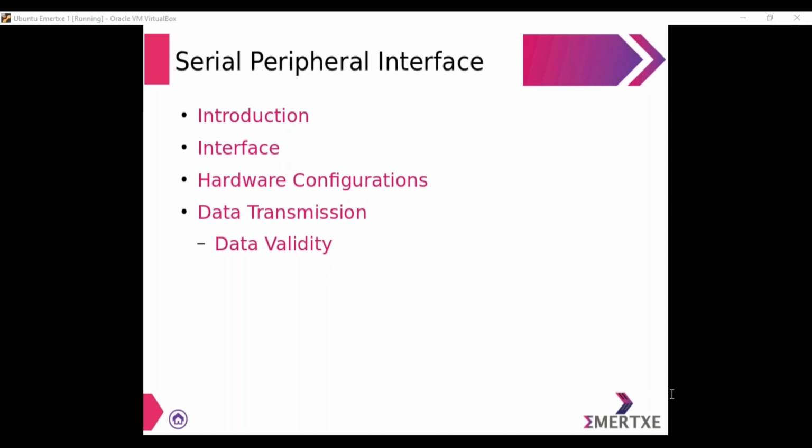Your question is, can't we print in CLCD using UART? You already have a CLCD which is done with the connection also. But if you are bringing a CLCD separately, you are bringing the microcontroller, and you are establishing the connection, then you may have to make use of UART.